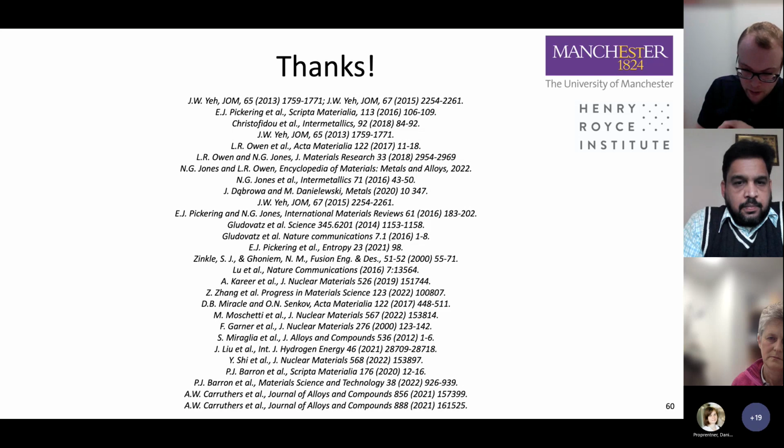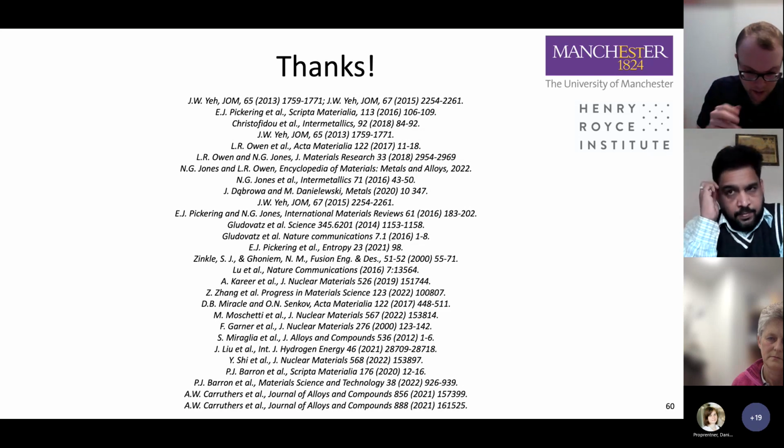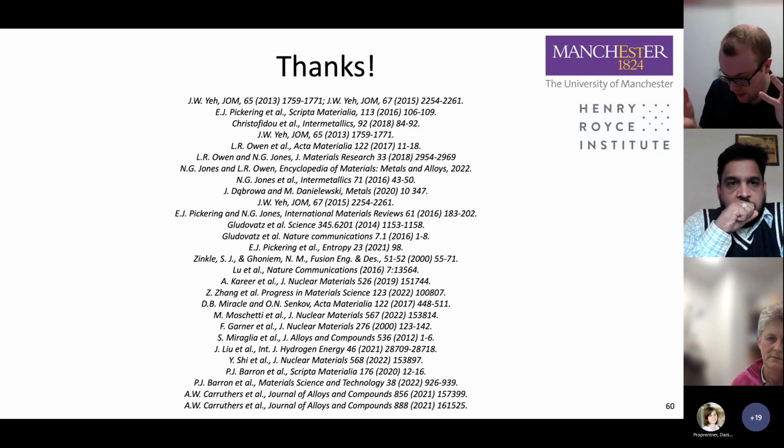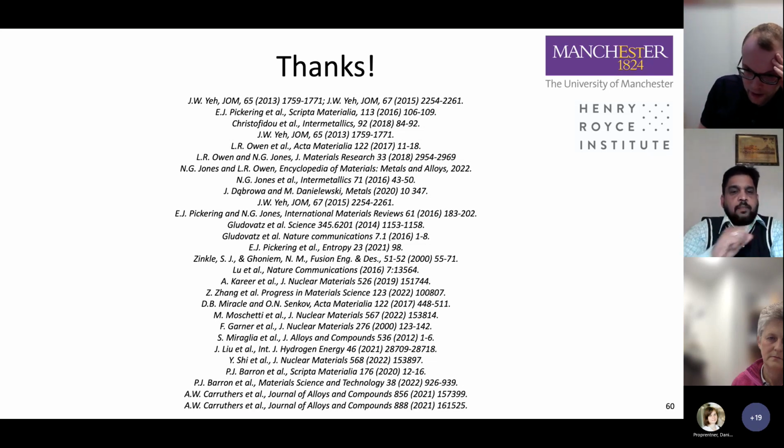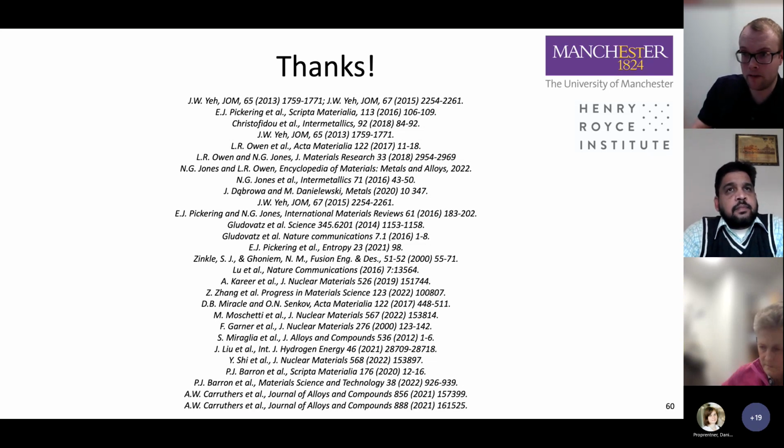Firstly, and this one isn't really about learning, but more about enabling research: a lot of the high entropy alloy work has forced thermodynamic database providers to assess much more rigorously their binary, ternary, and quaternary systems in a way that they haven't been asked to before.